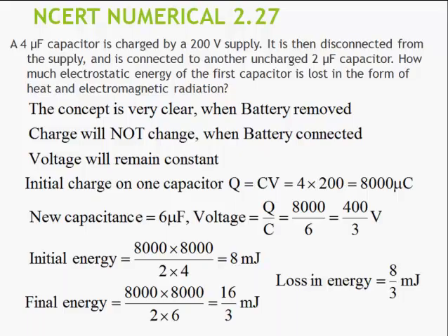In such a case, we are assuming that both the capacitors are connected with positive to positive, negative to negative. Secondly, you should always remember that energy will be lost in such combination, whatever you do, because where does the energy go? It goes in heat, light, sound. So you should remember the voltage has to reduce, the energy has to reduce. So this is all about this numerical.